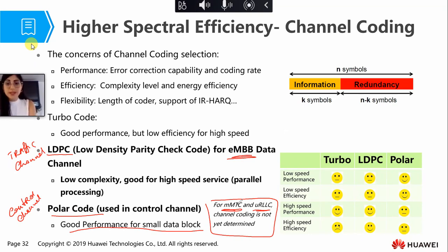It's not correct. Only for enhanced mobile broadband, we use LDPC for traffic channel and polar code for control channel, not for massive machine type communication or ultra reliable low latency communication. For these two scenarios, the channel coding is yet to be defined. Okay, so this is just an example.